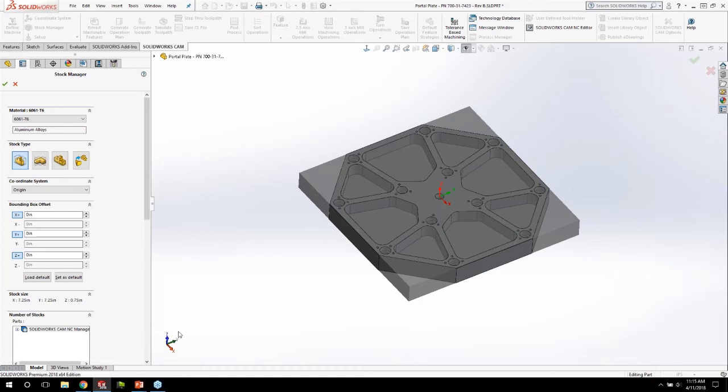So the great thing with this is if you imported a part and it's kind of off axis relative to this here, you can go ahead and create an actual SolidWorks coordinate system in SolidWorks and reference that here to go ahead and readjust that, right? So yeah, full control over how you want to do that.